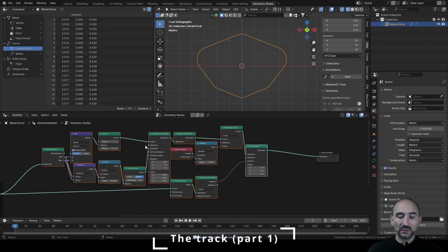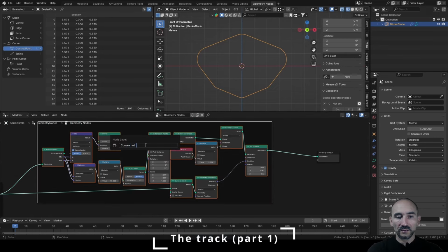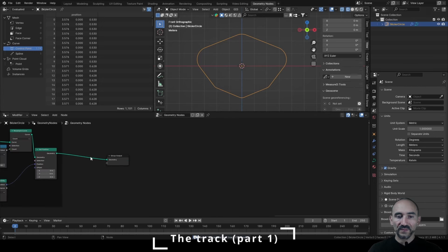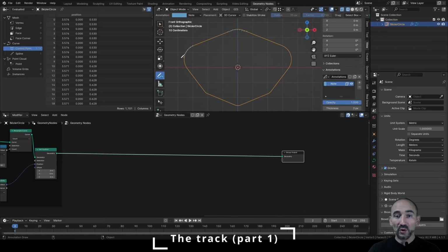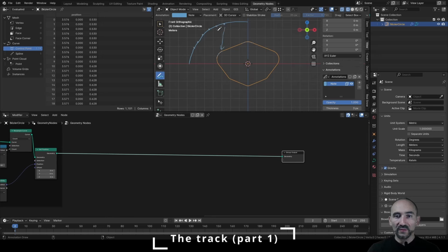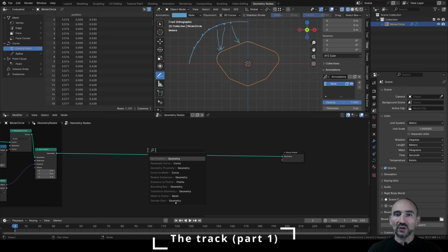We can select all these nodes, Ctrl J F2, convex hull for making the track. Now from this shape, maybe you cannot see it, but these 1000 control points are not equally distantiated around this object. So we have lots of points in this beveled part of the curve and very few points here near the linear part. Why? Because from the biggest curve, the geometry proximity took the points and moved them to the nearest point on the final curve. This means that we need to resample the entire curve another time inside our geometry to have a more correct distribution of points on this curve.